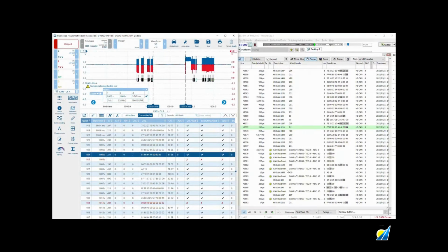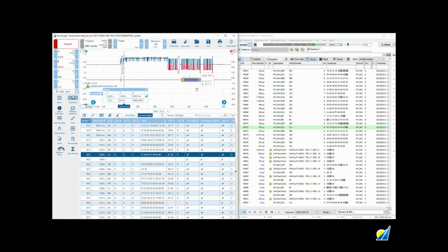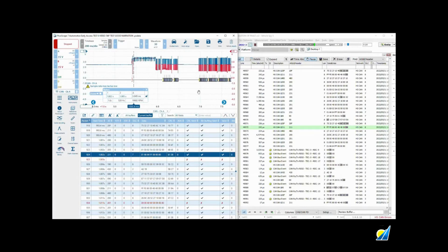Now we move on to the 190 message which comes through, and that was this one here. And that is a successful message. Another notification that the error counters are decrementing, which is great, because the 430 message gets through, and that correlates here. And these continue then to decrement because the bus, in effect, now has been restored.